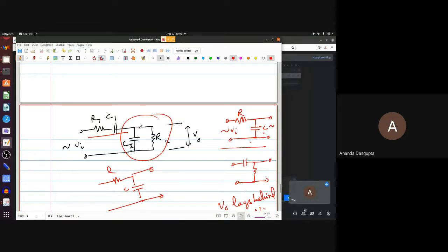If on the other hand you go to very high frequencies, both capacitors will have rather low impedances. But now this combination will look like the resistance, and this one will look like the capacitance. Remember, the output is being taken at the same place, but for low frequencies, it was as if you were taking the output across R2, right?